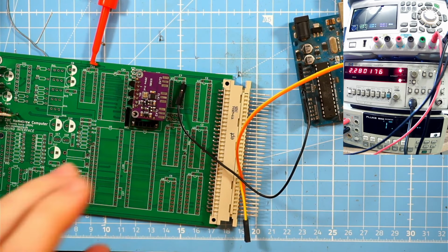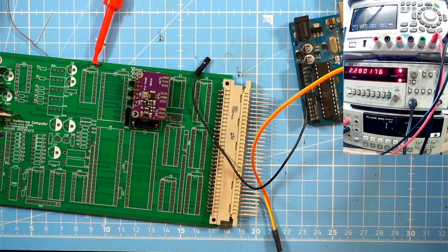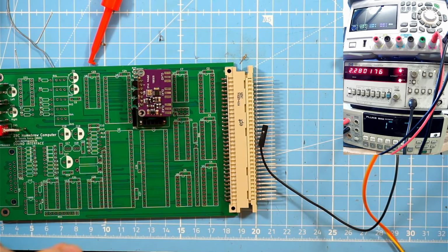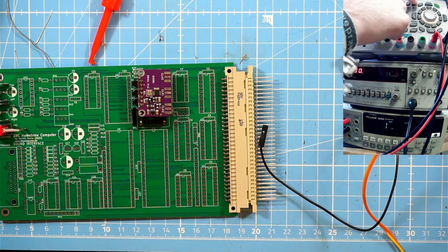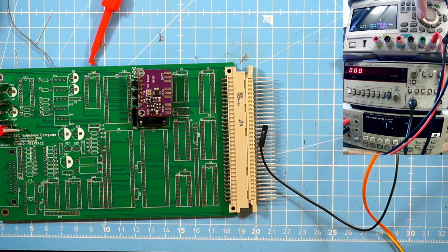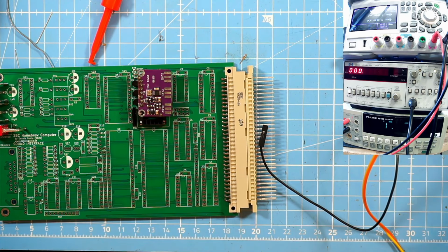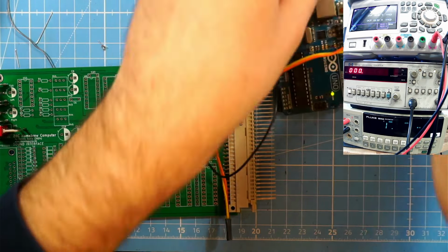Okay, I'm ready for a next step, which is to actually test if this is working. For this test setup, I've prepared my bench power supply and my universal counter. I can set this up to 5 volt, 500 milliamps. I guess that's too much. Let's say 20 milliamps. That's, I think, the least that I'm able. Okay. All right. Turn it off. Then let's hook this up.